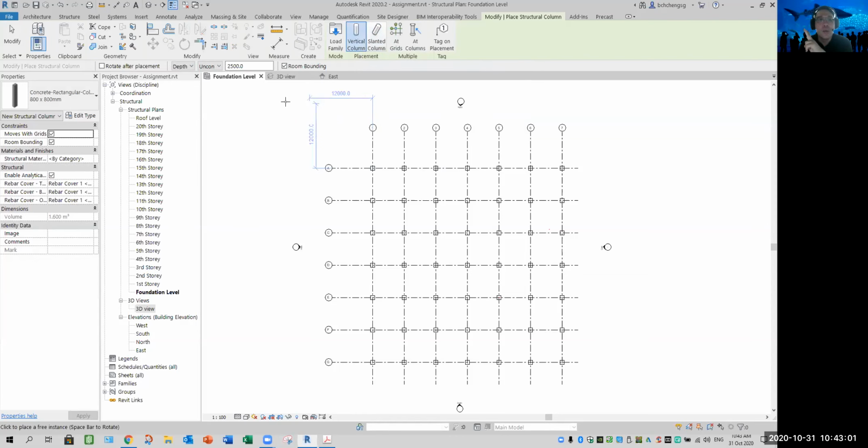Second, look at the options. For the structure setting, always go by depth. Meaning what? Now I'm creating from foundation. If you go depth, that means you are pushing your footing even lower, which is wrong. My footing is already at foundation level. The first story is here.